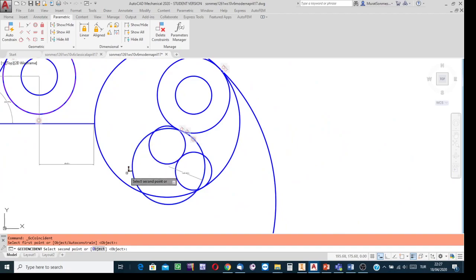But you should know the trick in AutoCAD: if we bring the cursor to the vicinity of a circle to indicate one of the points on the circumference, then AutoCAD, using its default configuration, will be ready to take its center point for our click.